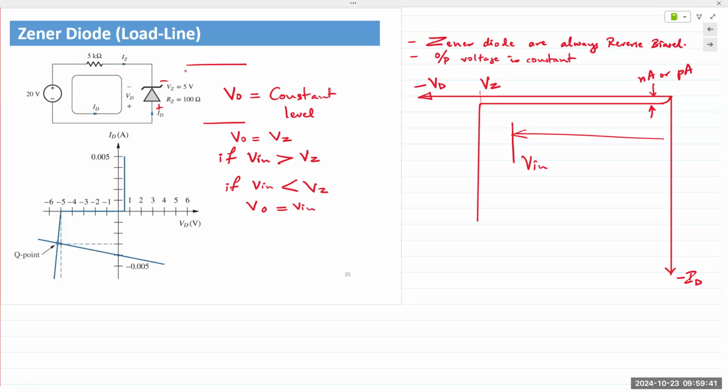Almost out of time. One final point is, so we had the rectified output. We gave it to a capacitor filter. Now we have a filtered output that has a small ripple. If the output of that capacitor is higher than a Zener diode that we are using, so let's say a Zener diode of 5 volts, and we apply a filtered output of about 6 or 7 volts. If we feed that 7-volt filtered output into a Zener diode of 5 volts, the output would be a constant flat line at 5 volts.